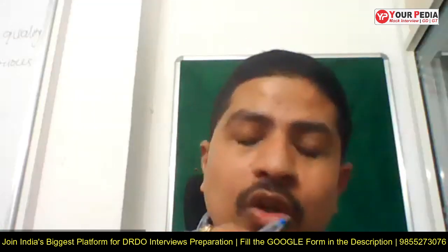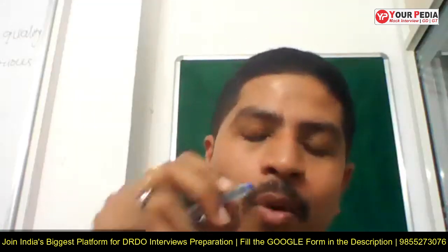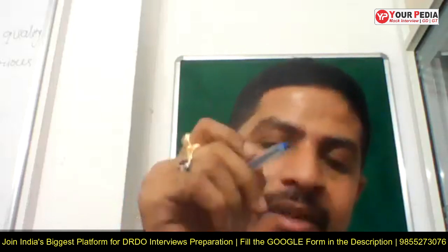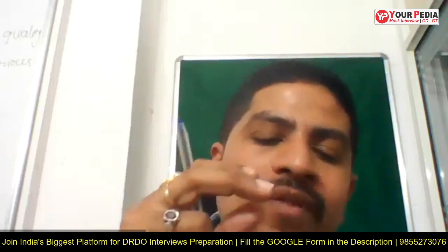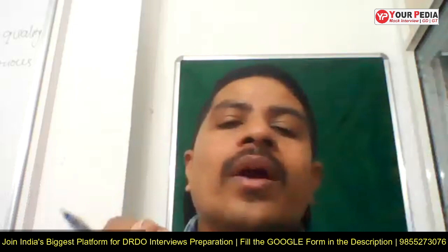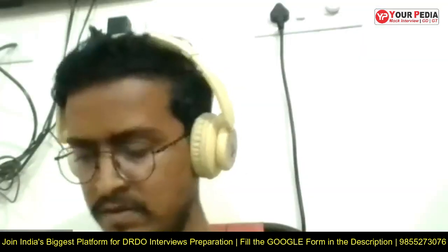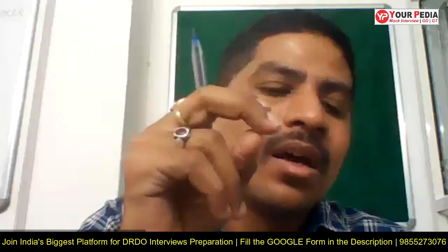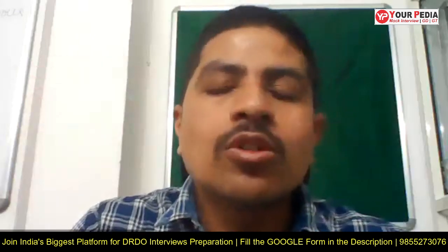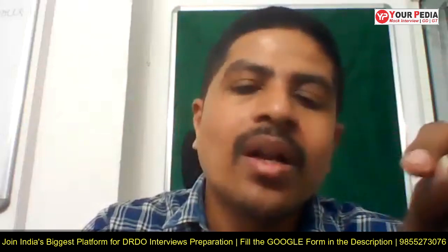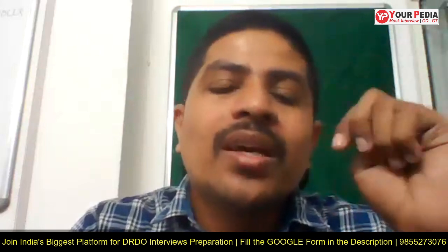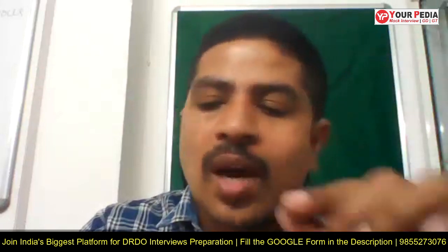So if you look there, we have a point where my straight line is intersecting with the root locus. There, give me the value of time constant and peak overshoot. And another point, which I selected on the straight line, there, what is the time constant and peak overshoot? Take those points as 1 and 2. The point where the root locus and the straight line intersect is point number 1, and the point for which I asked about transient response is point 2. Then give me the time constant and the peak overshoot for those two points.